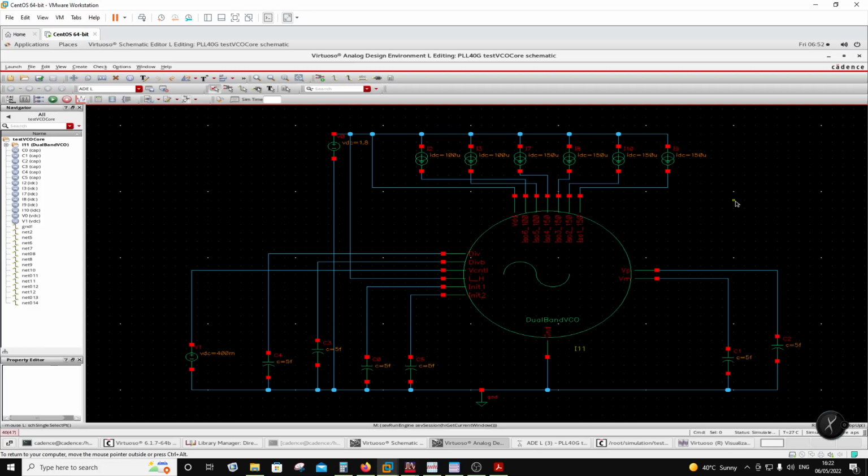Okay, so this is the idea on the layout. And the same thing I have done in the IHP SiGe process because this one, Silterra, is not space qualified. So for onboard electronics, they need space qualification. So I have repeated this entire project in SiGe 130 nanometer IHP, which is space qualified. So I'm going to do it in both.